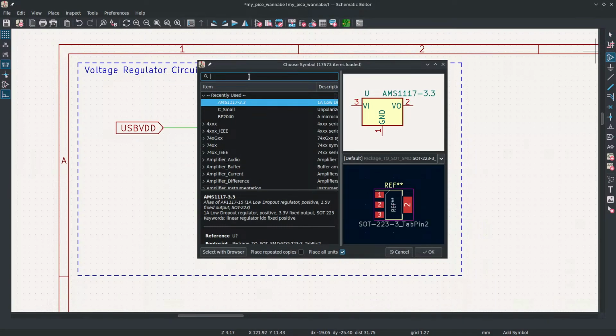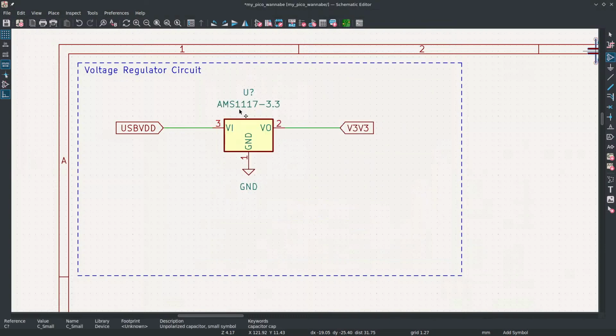I have some 10 microfarad 0805 capacitors, so we're going to use 2 of those instead, because I have a reel of them. You'll find that's really common on a board: a component duplicated. If you have a 1K resistor and you need 2K resistance somewhere, when manufacturers put boards together, it costs money the more different types of components you have. It can be better to put just 2 of a 1K resistor in series instead of having a whole new part number.